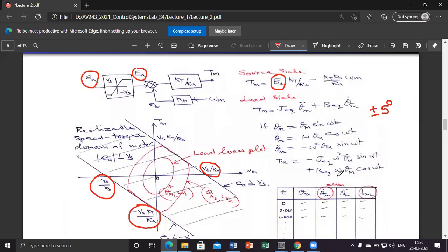So that is what I am going to show here. There is a special frequency-amplitude pair through which only you will deflect or steer the engine or the load. Theta m(t), you can say, is equal to capital Theta m times sine omega t, and we give specific values for theta m maximum and omega, so that the load dynamics will do the intended purpose.